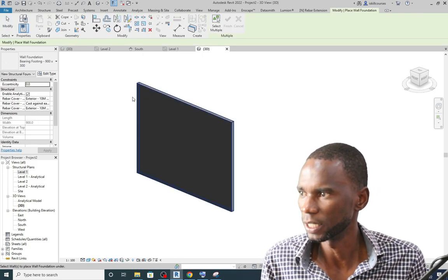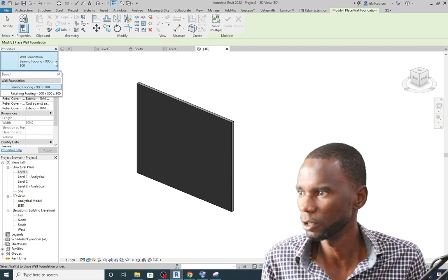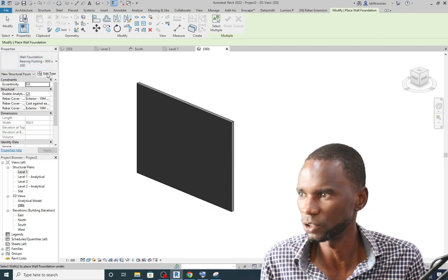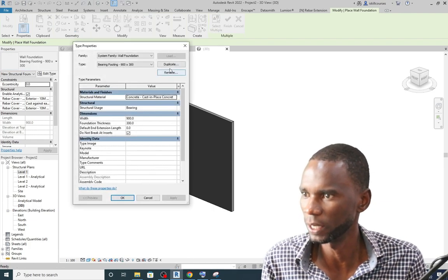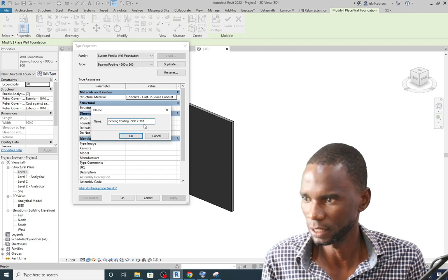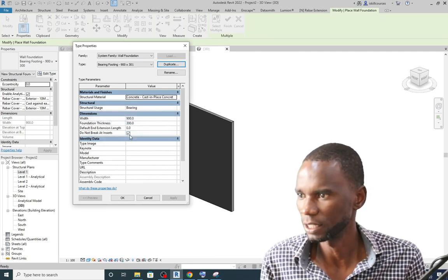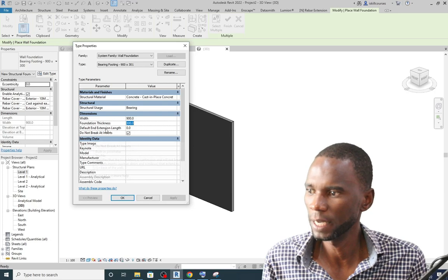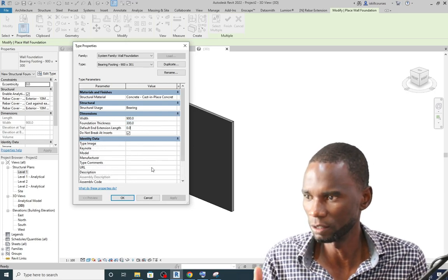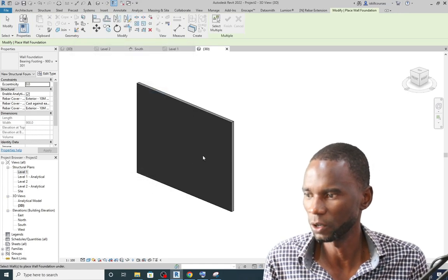I'll just select on that, and by default we have a 900 by 300. I think I'll still use the same. It's okay. If you want to edit it, you can go to Edit, Duplicate, give it a name here. I'll just maintain the same name. I'll just click on OK, and you can change the width and the foundation thickness from here. Now for the default end extension length, I'll show you what this one means. First of all, I'll leave it the way it is. I'll just click on OK.